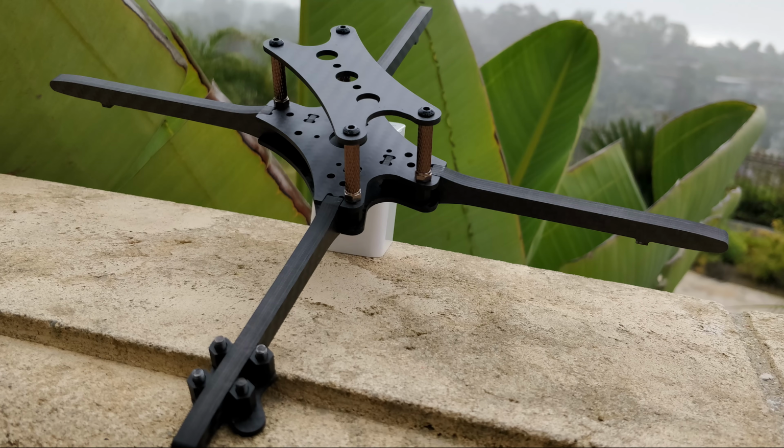In fact, I've talked to aerodynamics people, and they say vertical arms are actually drastically worse for what we are doing, because the attack angle of the arm is not acting like a wing. At the angles that we typically fly at, it's causing more drag than a flat arm because of the inverse angle of the arm.